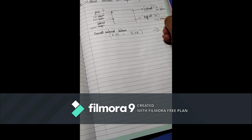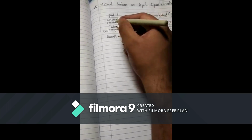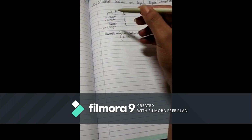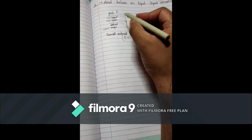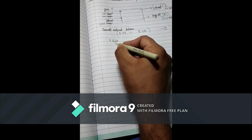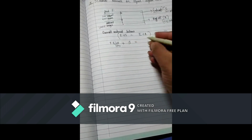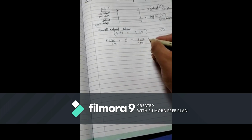So when you see that the concentration of toluene is given in everything which is going in as well as coming out, you can apply material balance on toluene. How will you do that? It is 20% of feed plus 100% of solvent, that is totally S, is equal to 30% of extract plus 40% of raffinate.